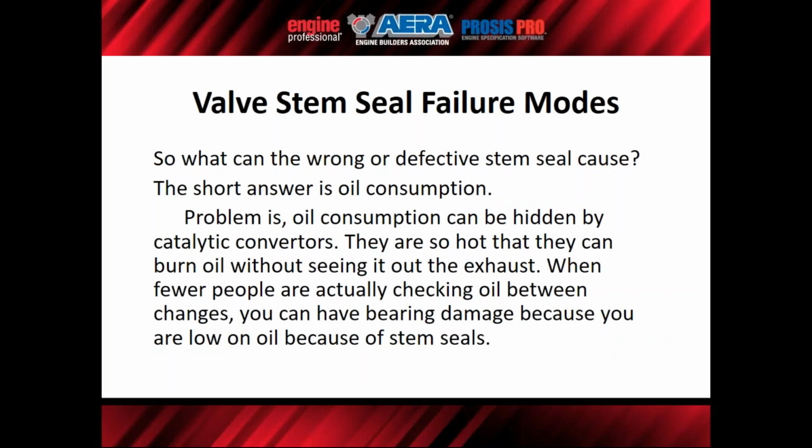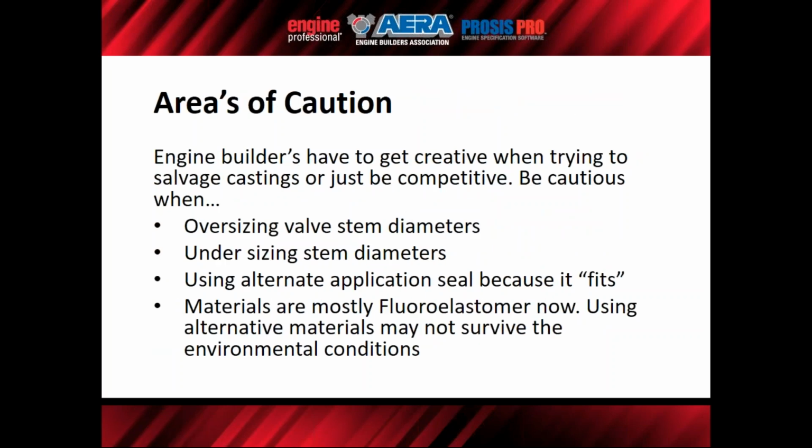You've got a 6-quart oil capacity, and the light comes on when you're at 1.5 quarts. So how long have you been aerating oil or starving bearings for lubrication? You can have rod and main failures because valve stem seals were the wrong application. They were defective. You had oversized stems that made them work like a bellows pump.